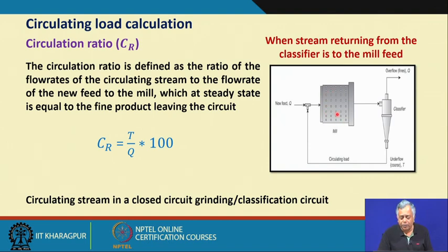Now, my grinding mill operation will have the best performance at a fixed or consistent percentage of solids. So, I have to check and calculate how much that circulating load is, so that I can control what the new feed should be, so that there is no disturbance in the relative percentage of solids and water, as well as the total charge, that is the volume occupied by the total charge, where you have got the steel balls.